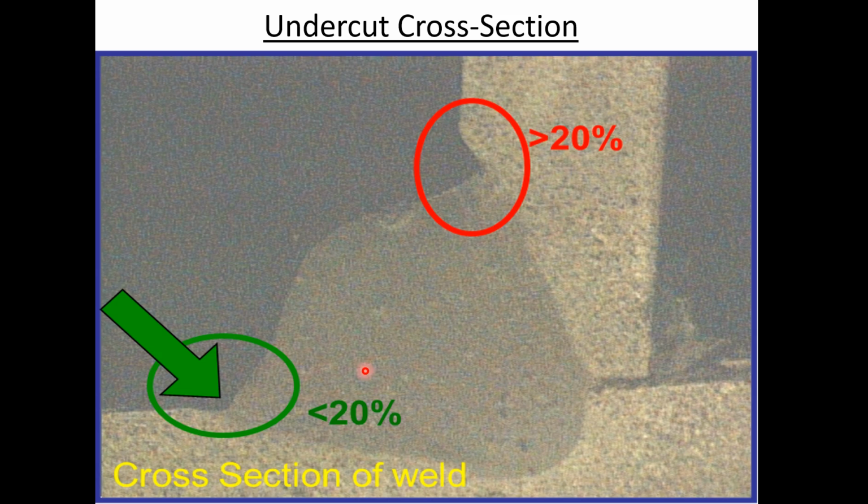These things are found in specification. Your responsibility is to take the information we give you by border sample or pictorial, or maybe even a gauge of some kind, and make a determination whether another weld goes into place. This is the good part about undercut. Much like an off-location weld, all it would take is the reprocess of a little bit of a weld right there, and it's good.